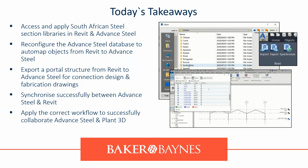If you don't have it installed or you don't have a South African Steel library, which will be pretty weird, you can also download that from the Autodesk Knowledge Network by simply typing in Google South African Steel sections Revit download. You'll get the first link, click it, download it, install it, you're good to go.